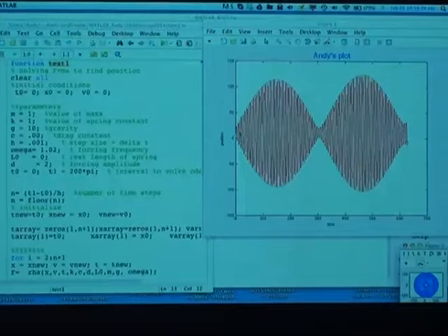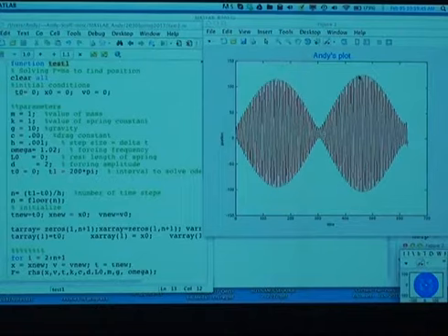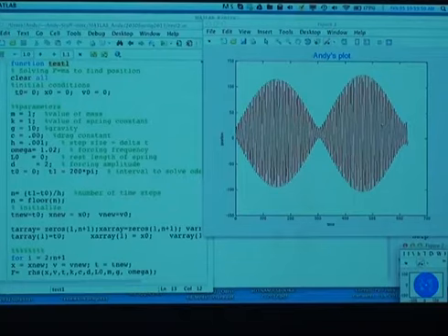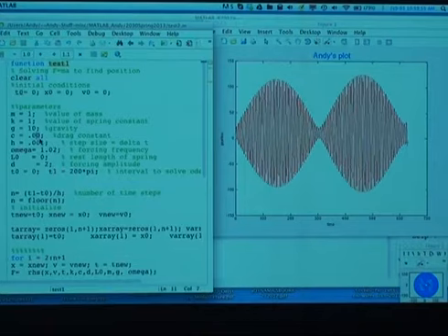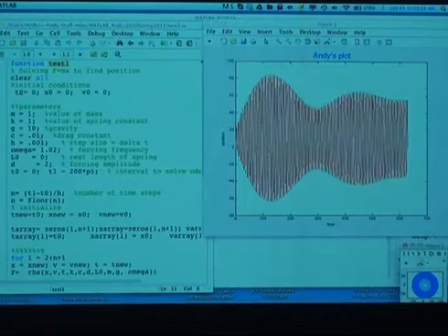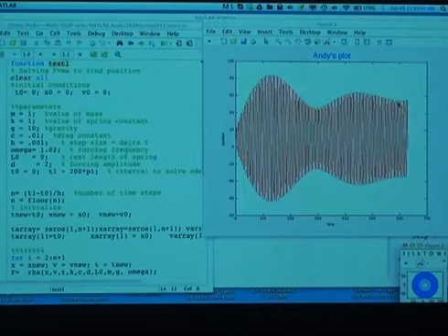What happens is if you just look for a small amount of time, it looks like resonance, and then it gets all eaten up again, and then comes back and gets all eaten up again. And this is a very mathematical thing, because it only happens if you have no damping. You just put in a little bit of damping, and then being close to resonance means it increases up to some steady state. So eventually that just levels out at some steady state.